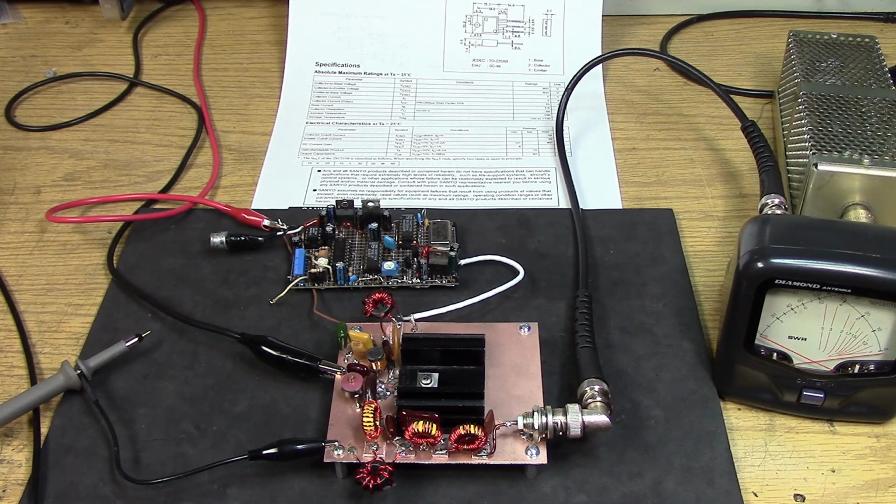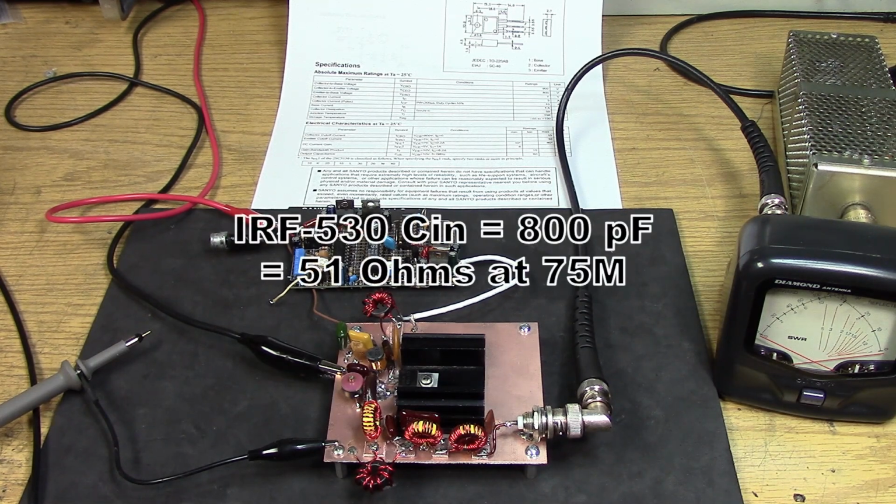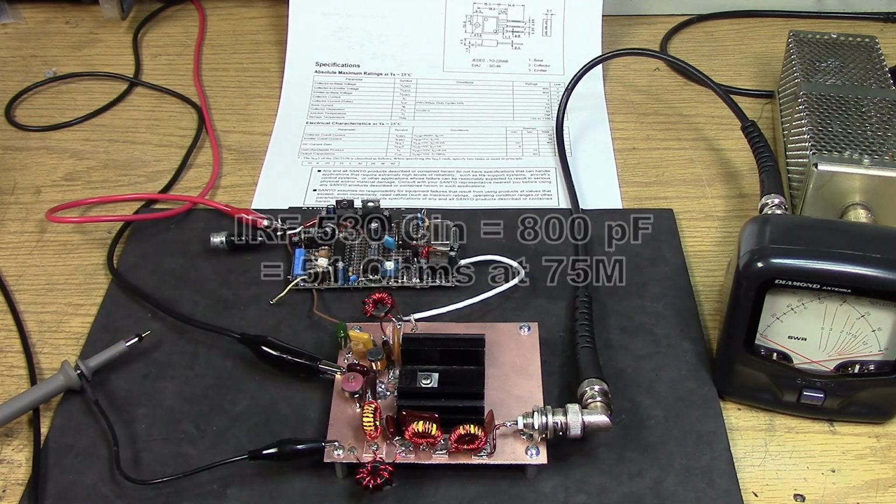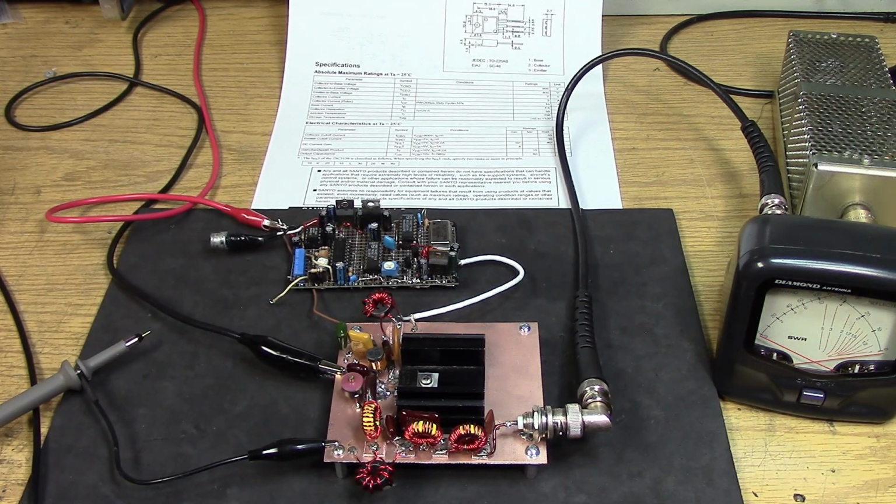We talk about the FETs as having very high capacitance. Typical capacitive reactances could be in the 40, 50, 60 ohm range. And we know that our little driver was driving a 47 ohm resistor quite nicely without any trouble. However, it probably would not be too happy trying to drive a 3 ohm or a 4 ohm or a 10 ohm input of a bipolar transistor.